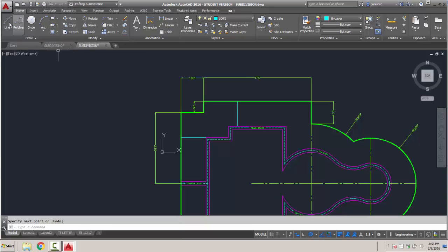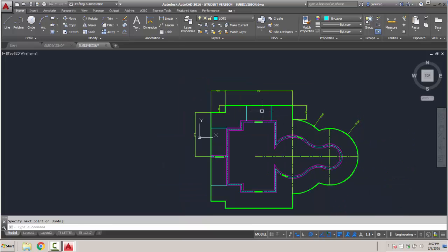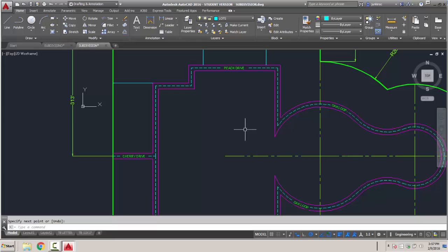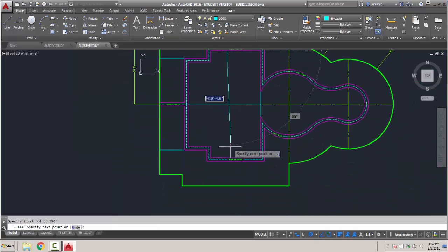And same thing from the other side. We're just going to lock it in here, bring it to the left 150 feet and come straight down, lock it to the road. We've got a lot line connecting this endpoint and this endpoint. We've got a lot line going all the way through the middle off that endpoint, and then we've got, it's 150 feet off this corner. So we'll just lock it in here, bring it over 150 feet, and then just go straight down all the way through both of these. So there's 4 lots in the center.